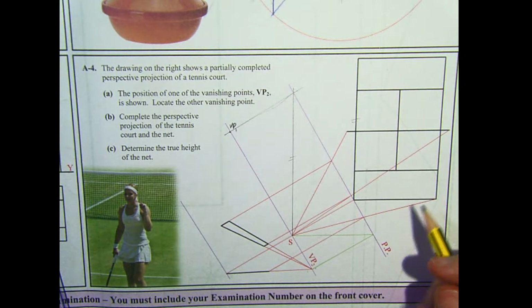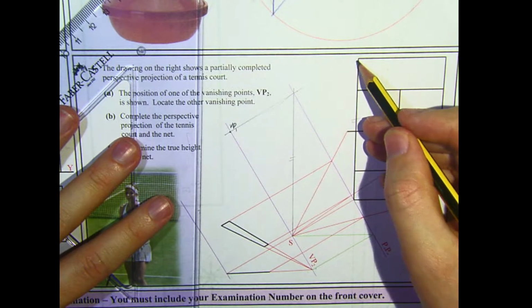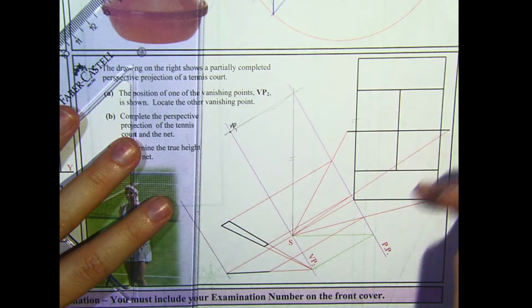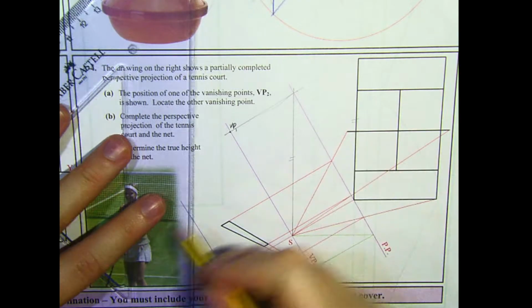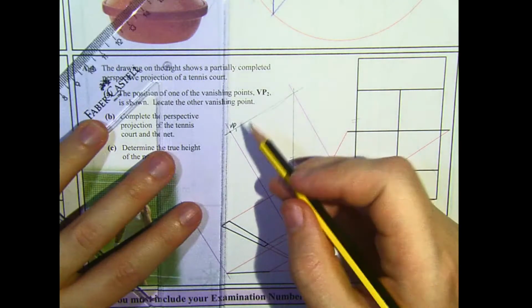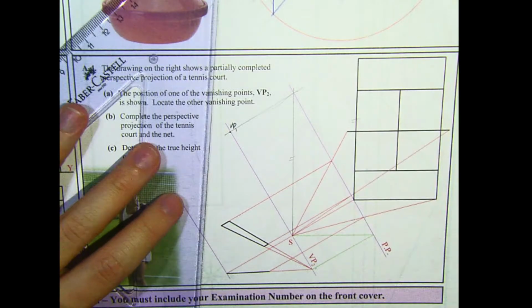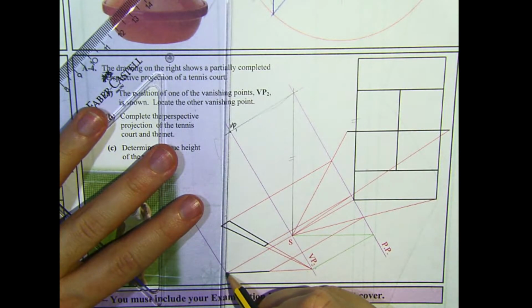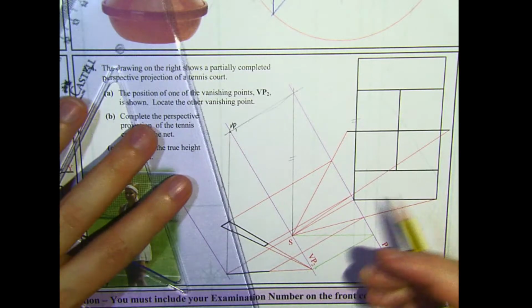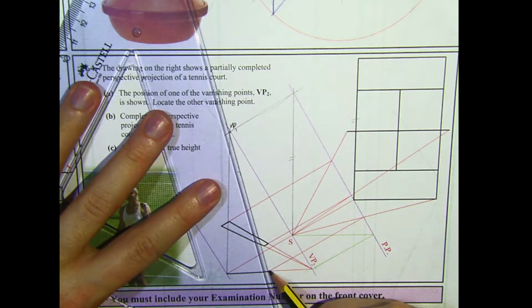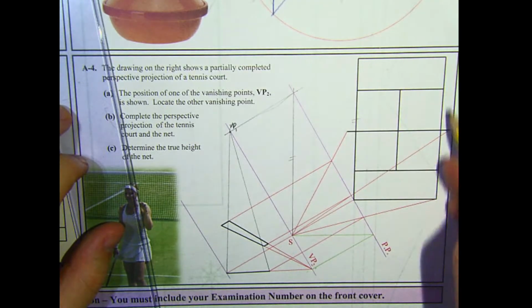Part B is to complete the perspective projection of the tennis court. So we're going to be bringing points from each different point up here to the spectator, and where they cross the picture plane are projected down into the perspective view. Now this corner here is this one of our drawing, and this is along this edge, so that's going to join back to the vanishing point on the left. So this is a line going to be back here. We need to work out where it disappears, and we'll do that in a minute. This is going to come back this way as well, so back along there somewhere. So that's this edge and this edge drawn.